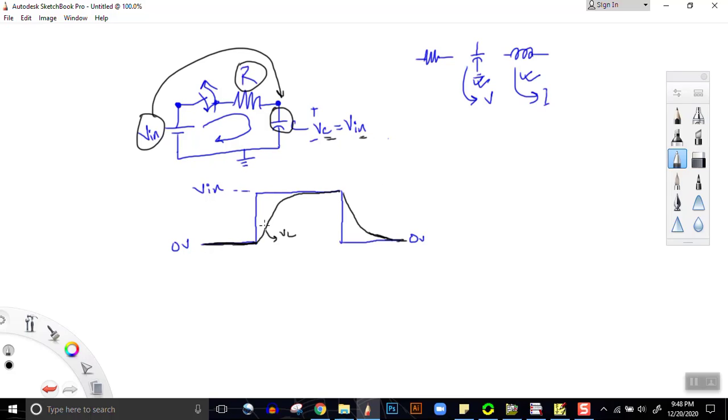Now the curves that you see here and here are exponential curves, and since this is a curve of Vc, the expression of this curve is Vc equal to V in, which was the initially charged voltage, times e to the power minus t by tau, that is, exponentially decreasing.